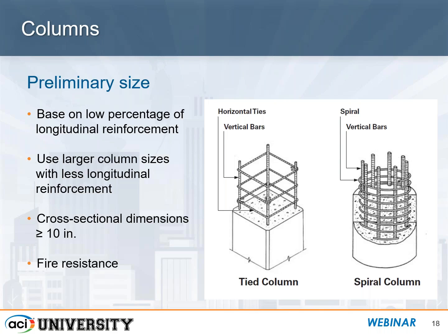So, determining a preliminary column size. As we know, we have different types of transverse reinforcement that we can provide in a column. Ties are certainly popular. Spirals are popular in some conditions. One of the constructability issues, as I'm sure you're aware, with the spiral column is that when we have a joint, especially with beams coming through that joint, we can have an issue with the longitudinal reinforcement interfering with the spirals, especially for the very tightly wound spirals, 2.5 inches on center.